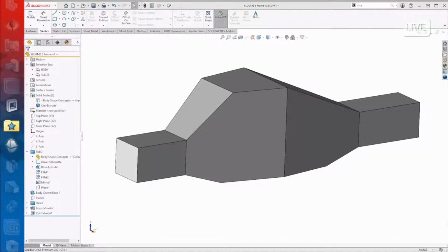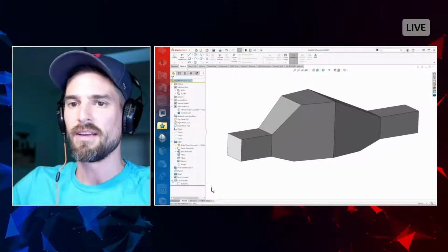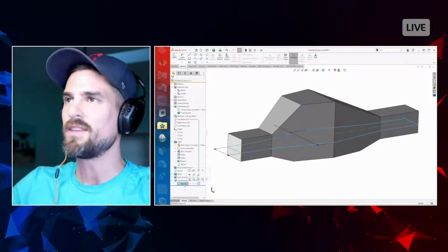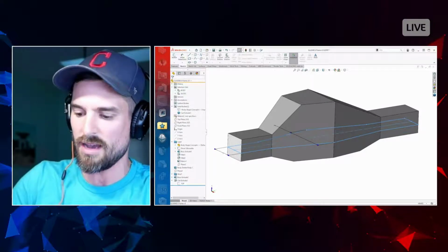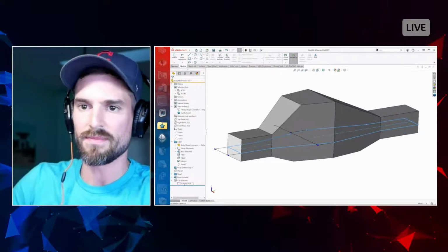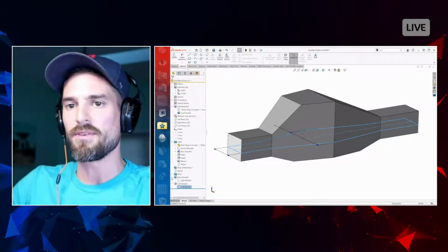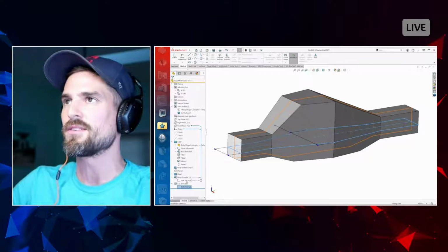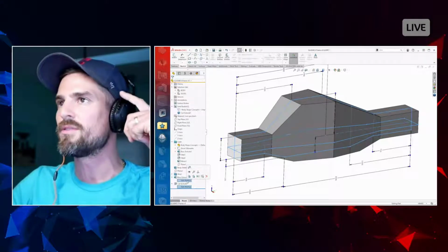So what defined this geometry? It was the two sketches. And what if I wanted to change the top profile? I would have to come searching through here and I'd be like, oh, sketch 12. Name your critical sketches, right? Definitely, so let's just call this top profile. Love it. And what about the side profile? If I want to change that, it's nested inside of this feature. It's kind of hard. Like, oh, I've got to remember it's boss extrude 2 and so on.